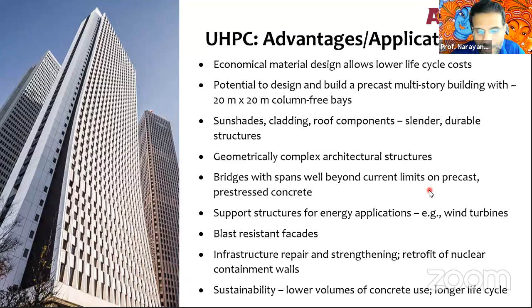Sustainability, I just put it at the end. I know everybody wants to see it first and foremost. It's not because it's not important. I just put it at the end because there are still questions that we need to answer, based on what we know about this material yet, about its sustainability. But in general, because you can make the cross-section smaller because this concrete is very strong, you can have lower amounts of concrete. Lower amounts of concrete translates to lower amount of cement. So you can better control the cement consumption and increase the sustainability of such structures.